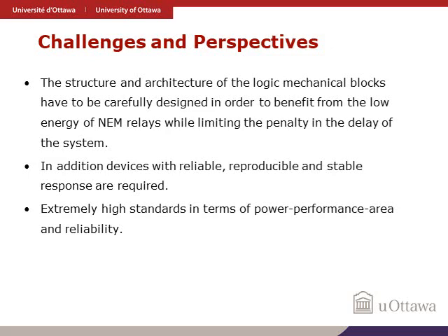So next are the challenges and the perspectives. The structure and architecture of the logic mechanical blocks have to be carefully designed in order to benefit from the low energy of NEM relays while limiting the penalty in the delay of the system. In addition, devices with reliable, reproducible, and stable response are required. Extremely high standards in terms of power, performance, area, and reliability.